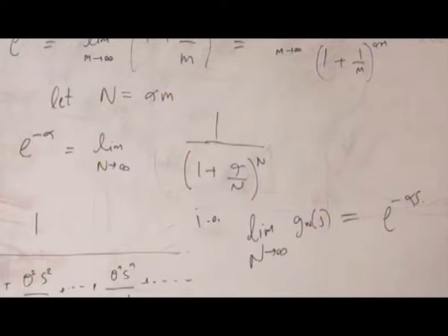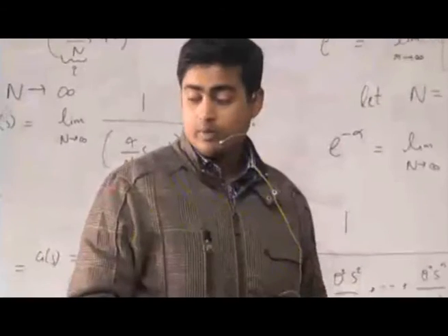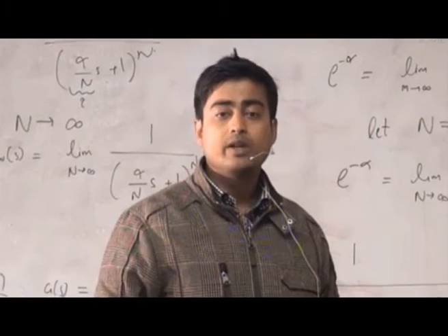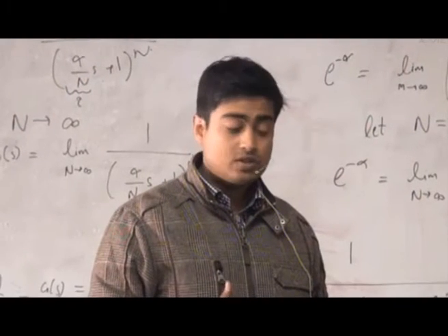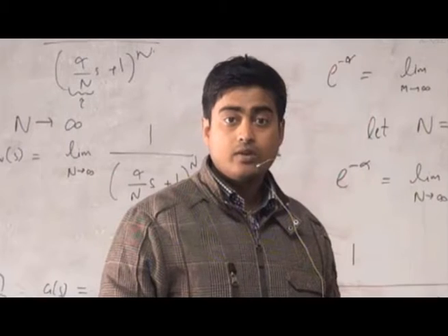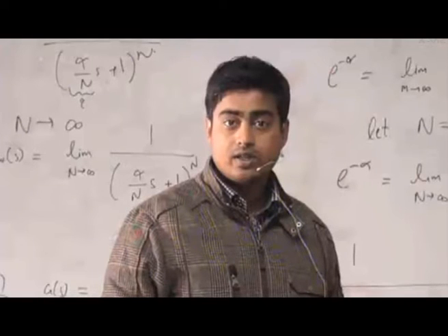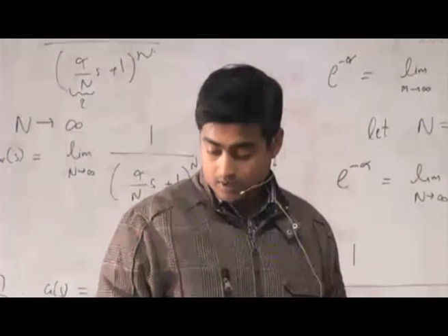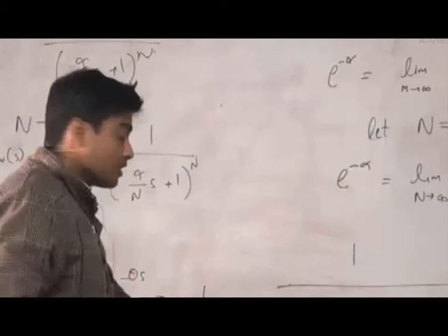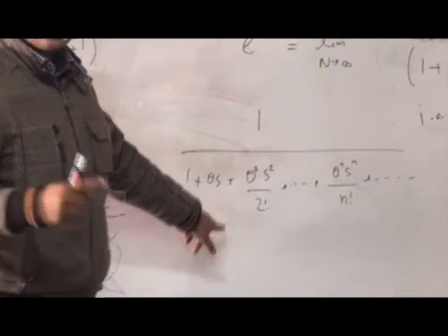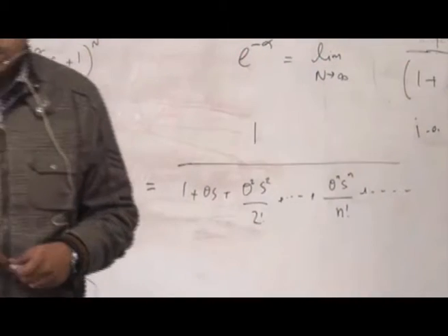But while designing a control system, it is difficult to analyze that, and what we have been looking at so far is either the first order system or the second order system, or we try to limit ourselves to those. Even if it is a higher order system, we can approximate it to a first order or second order system, so that we can design a control system accordingly. But since you have a delay in your system, as we have seen, it brings us to an infinite order system. So we need to approximate it to a lower order, and we'll see how.